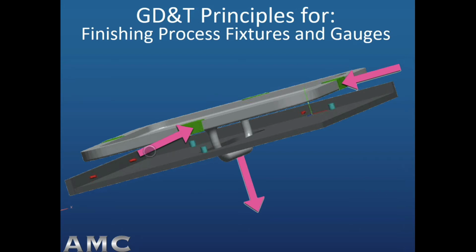There are also pins here on datum B, 2 pins, which are the secondary datum targets, and they touch the casting, and notice that they are smaller. They touch the casting on the drafted surface. So if the casting sits flat on the datum A targets, then the draft on this surface doesn't matter because these smaller pins will touch the casting at the same elevation.